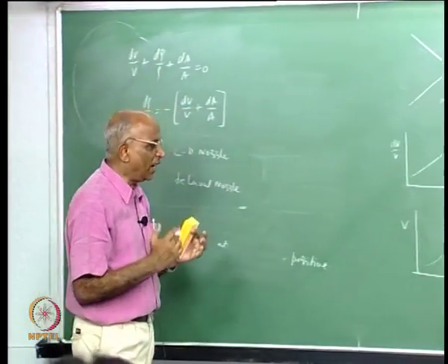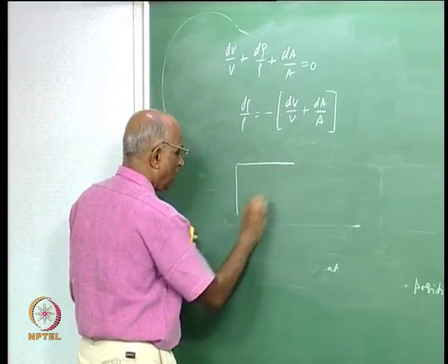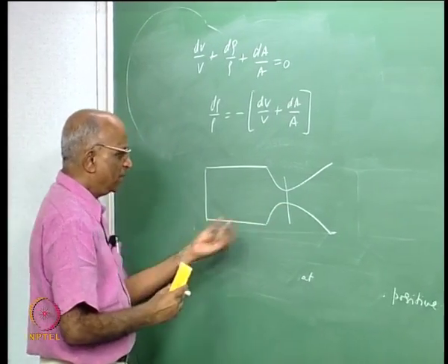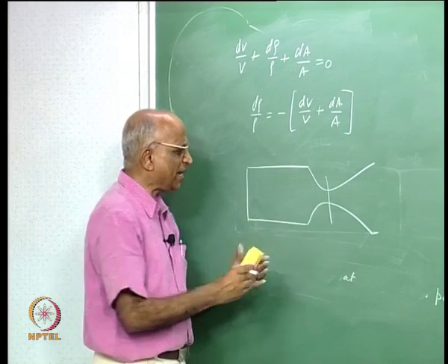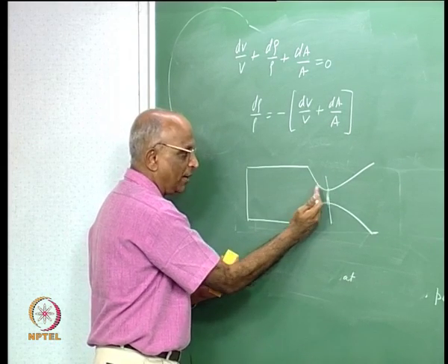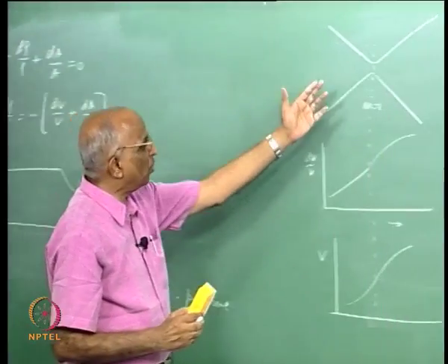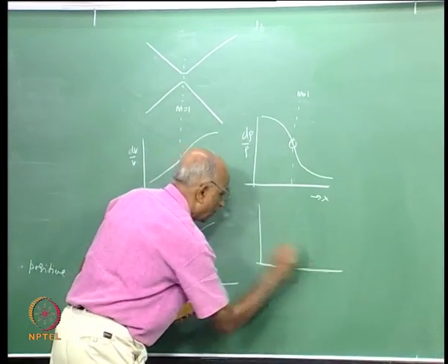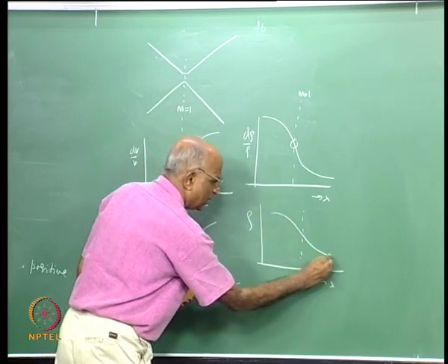In fact, when we get into this problem of combustion instability, we will find that when we have a rocket with a convergent divergent section like this, the rapid change in density over here acts as if it is a solid. There is a very rapid change, therefore it tends to be a closed end and not an open end. We will come back to this, and this is important. That means at the throat portion you have a large change, and therefore if I now plot my density as a function of x here, I have the throat over here, well, the density keeps decreasing.